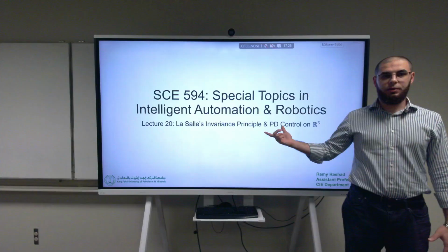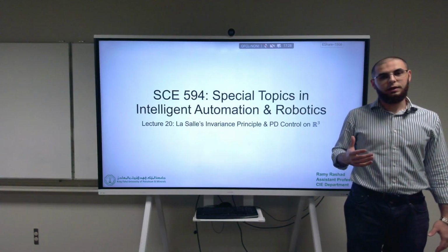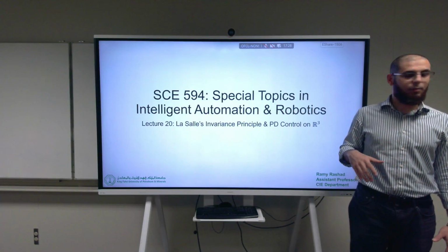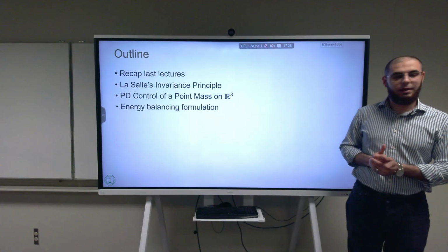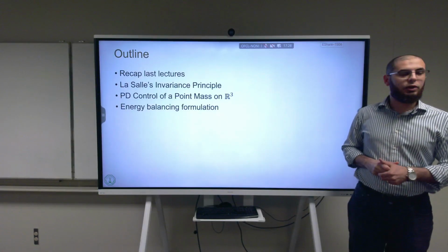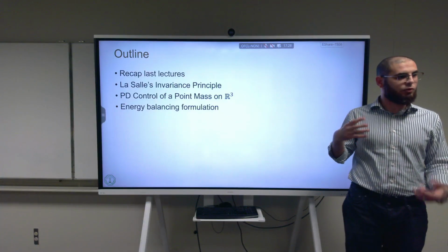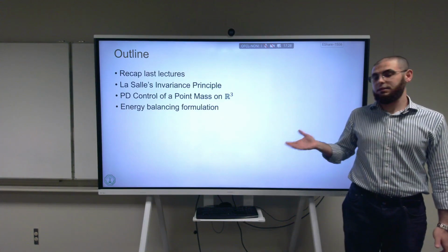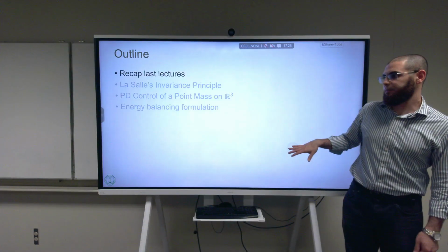We're going to wrap up the analysis part with another concept or principle called LaSalle's invariance principle. So this will be an extension to Lyapunov's direct method. So the recap, as usual, and then we're going to be looking at LaSalle's invariance principle. Then we're going to be looking at the PD control of a point mass. So we're just going to be reinterpreting PD control in the simple Euclidean case. Next lecture, inshallah, will be where we try to do it on SO(3) in a geometric way.